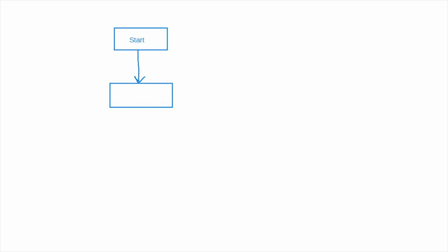In the setup function, that's where you declare your pin configurations, because most of the Arduino pins are multi-purpose. They can be used as an input or output, and some of them have other functions as well. So in the setup, you define how you are using the IO pins.